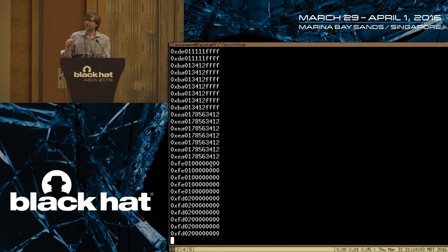I would just need to verify that by trying a few more codes and making sure I have the checksum algorithm correct. Once I know the checksum algorithm, then it's very straightforward to make a little encoding function where I can increment or brute force the PIN. Good question. That's the kind of thing that only takes a few lines of code in RFCat, but could be a lot more complicated to accomplish with software-defined radio.